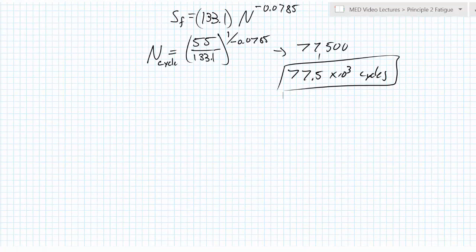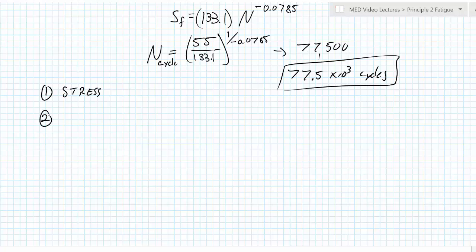So the process goes, for our fatigue analysis, we do, what is the stress. So this is from mechanics of materials. From the stress values, we figure out what is the mean and amplitude. From the mean and amplitude stress we can then apply our failure theory, our fatigue failure theory to be exact.